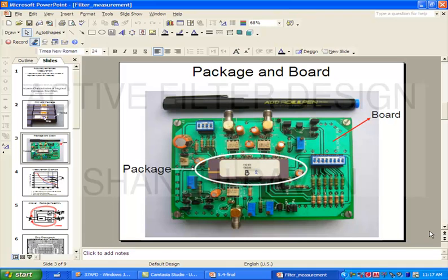We need various stuff like supply, right. You need bypass capacitance between supply voltage and ground. In your lab you probably have seen what happens to circuits when there is no decoupling of the supply, right. So for example, all these big electrolytic capacitors are examples of decoupling capacitors. Then perhaps you need a clock for a DSP. This only consists of a filter, so it does not require a clock. Some switches, let us say you want to set some bits to ones or zeros, there are some switches, these are examples of switches you can set on the board, right.